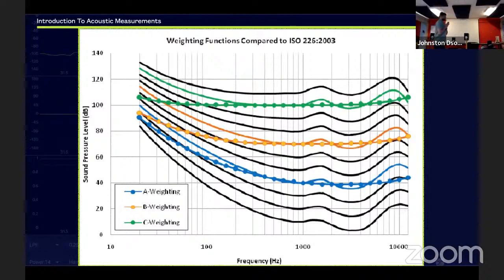There is another thing in average, something known as LEQ. Because in audio we are on a logarithmic scale, we cannot directly calculate average. So there's another algorithm that takes care of all the averaging. We are working on an SPL meter which does not have that capacity. But if you're working on proper software, you can set how much time you want to measure for. Say you want to take average readings for every 10 minutes or every half an hour, the software will measure for half an hour, and every half an hour it will keep refreshing the readings.